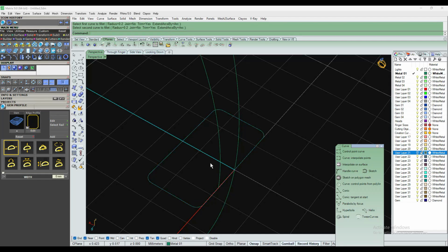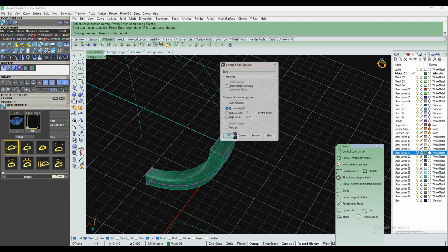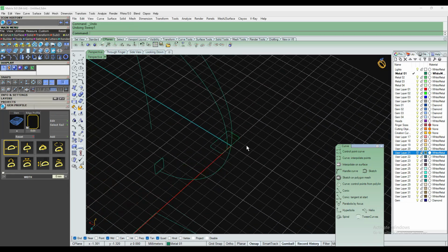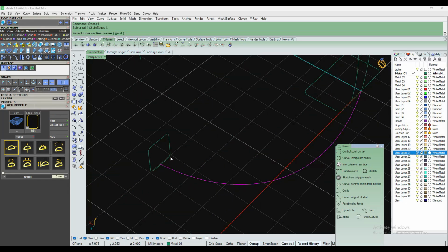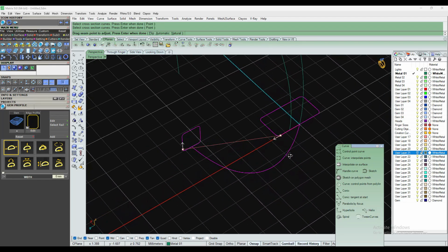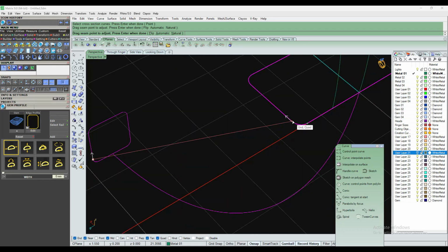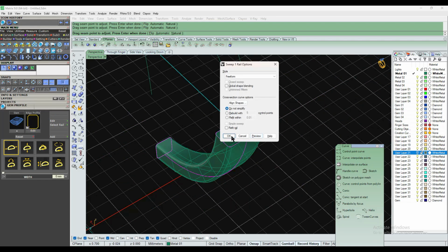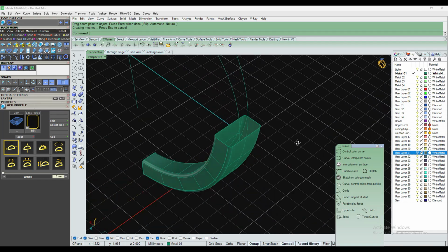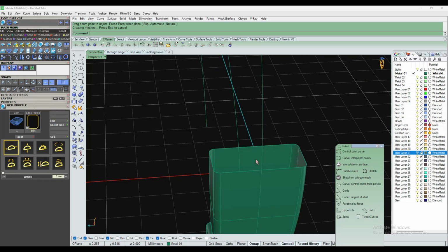And okay, so you can use the Sweep 1 option and connect this curve from here to here. Okay, and if it is okay, let's undo, select both the curves. If the ends are matching, see, ends are not matching, so let's bring this end to here. So now the same ends and the profile will go the same. Okay, now we need a separate profile for these two cross sections.